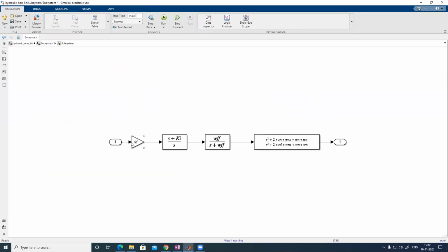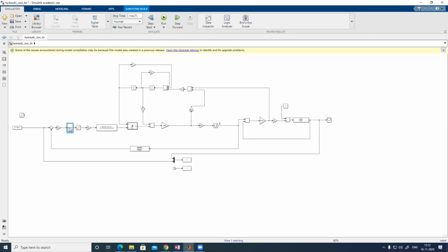So click on this one, you can see that this is a subsystem. So you can create the single transfer functions, cascade them, select all the things, then the 3 dots will come, and you can make it a subsystem. This is the easy way to do it. That one is the subsystem. This is the compensator.